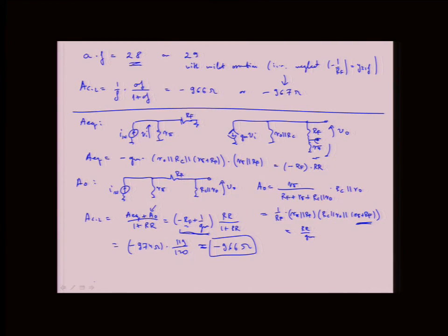That's exactly the factor, RF plus R pi, or RF in the other case, but here it's a bigger divider than in the previous case. In one case you're dividing by 120, and in the other case only by 29. But when you're dividing by 120, you're dividing a bigger impedance, which is RF plus R pi. So it comes to be the same thing in the end.